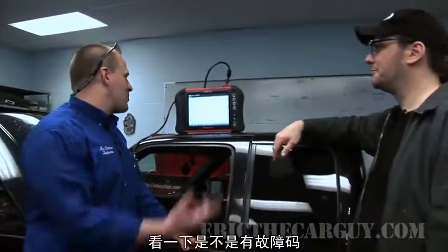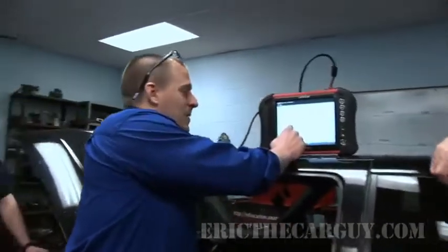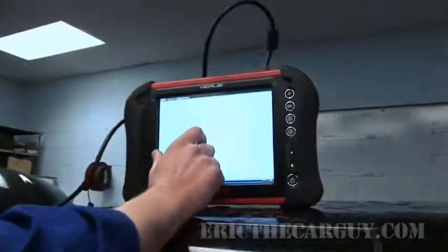And so for a misfire, OBD2, we can get a little bit of help from a trouble code sometimes. Pre-OBD2 cars, of course, really not too much help with that. Anyway, we don't have fancy machines we can hook up, but we can still use the tool between our ears, right? So we're going to hook it up and look for codes. Display codes is where we're going.